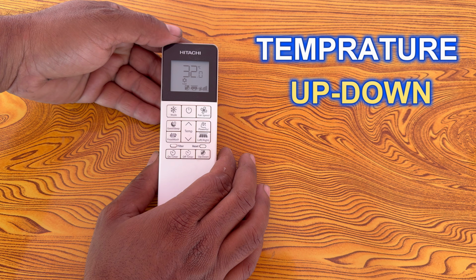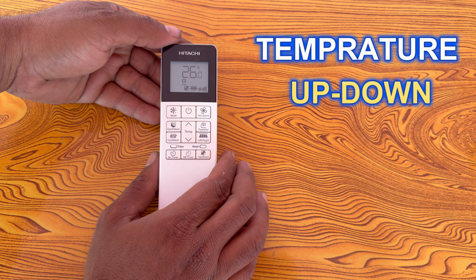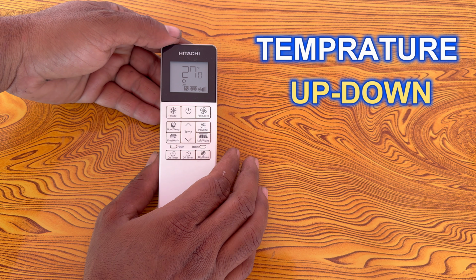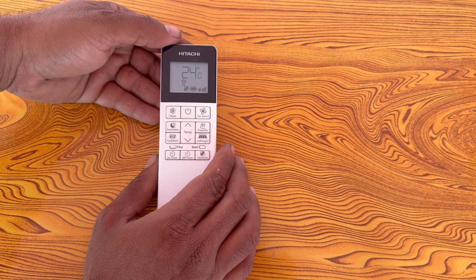If you only need cooling and want to reduce your electricity bill, use 26 degrees. This is also a very good temperature for our body. If you find 26 degrees too cooling, set your AC's temperature to 27 degrees. And if you find 26 degrees too hot, set your AC's temperature to 25 or 24.